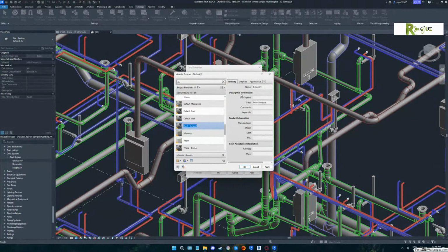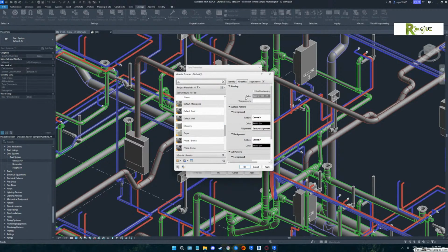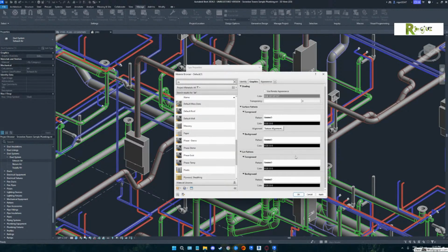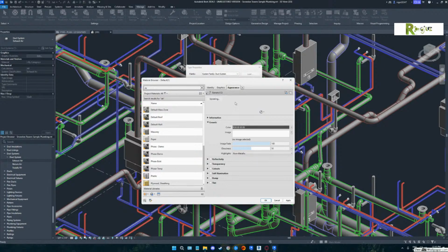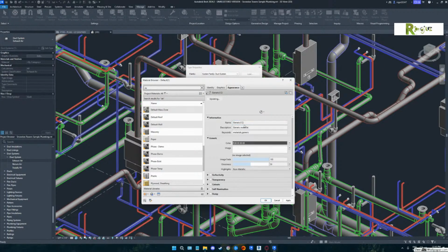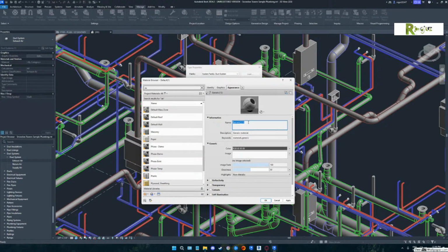Now what we do is on the graphics. That's pretty neat how that one didn't start out in the graphics mode. We would use our render appearance. Okay. And then we would go to the appearance. You got to hit that. They still got to do that. Now, I don't believe you have to duplicate it. Remember how I always made you duplicate it? But I would still duplicate it just in case. I think it did that when you did the duplicate with its assets. Now, highlight generic 13. Now go to the color.